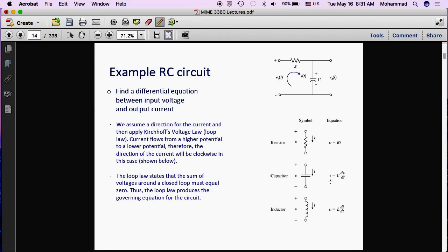So just simply looking at this equation, if current is the input and voltage is the output, you can see that the voltage wouldn't immediately jump. The rate of change of voltage is proportional to the current you apply, so there is a delay. Can you see that by just looking at that equation?